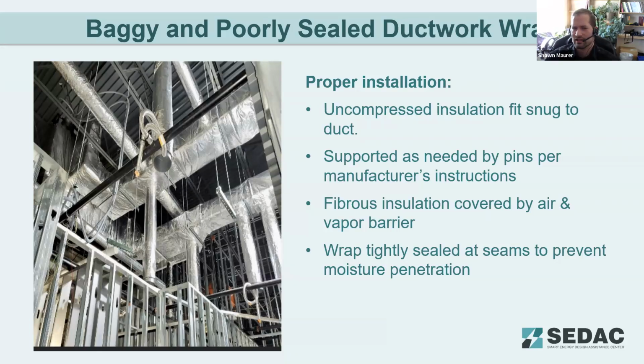There are other adhesive sheathing systems out there. VentureClad is just one of them. But for energy code compliance, the main issue is whether the cladding is an integral part of the insulation, in which case it's permissible to install. If it's not an integral part, it's an add-on product for the protection of whatever insulation was installed. If you've got board insulation in place and you're wrapping it with this VentureClad, now that's an adhesive tape and it's not permitted by code. So there's a fine delineation there between the applicability of that type of cladding system, whether it's permitted by the energy code or not.